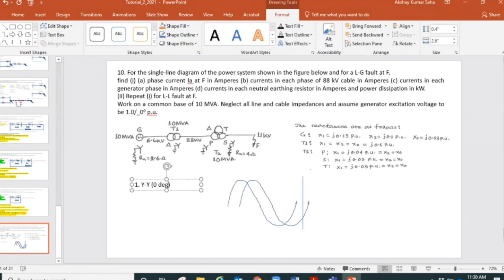That can be explained in that other class that I mentioned. So when I don't need any phase shift, or cannot have any phase shift, between the voltages from the primary side to the secondary side of the transformer, I must choose Yy0, and I can do that by connecting the windings of the transformer in a particular way. I have to know that as an engineer, because if I just go and connect them in star, that will be a disaster. And that's what we do in our practicals in the universities. Without knowing, we just go and connect them in delta, we just go and connect them in star. That's a disaster to me. I cannot do that. No one should do that.